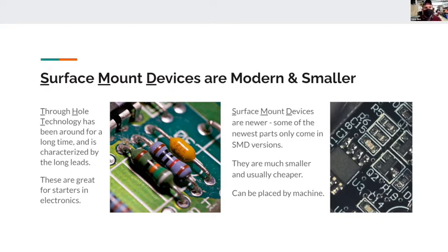Like I've got right here a little baggie of SMD resistors. And so these are 330 ohm resistors. And if you've played with those in the space, these are the exact same specification, 330 ohm resistors with a 1/4 watt and 1% accuracy value. And look at the size of those. I know you can't see this hardly at all, but it is very, very small. And so they're 12 by 6 or 1. Well, yeah, we'll get into sizes for those in a bit. But they're very small and they come in much cheaper.